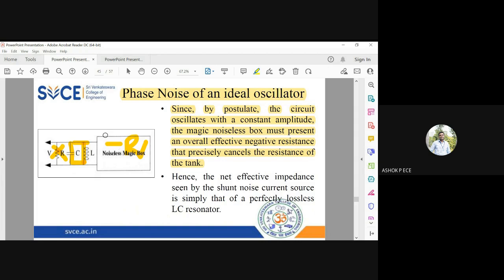And about this negative resistance, you cannot physically see a resistance with a value of minus 1 ohm or minus 2K. What negative resistance means is this: by Ohm's law, V is proportional to I. So as your voltage is increasing, the current should ideally increase. That is the ideal amplifier. This should be the ideal case. But in negative resistance, as the voltage increases, the current will start decreasing. So this decrease in current is denoted by negative resistance.